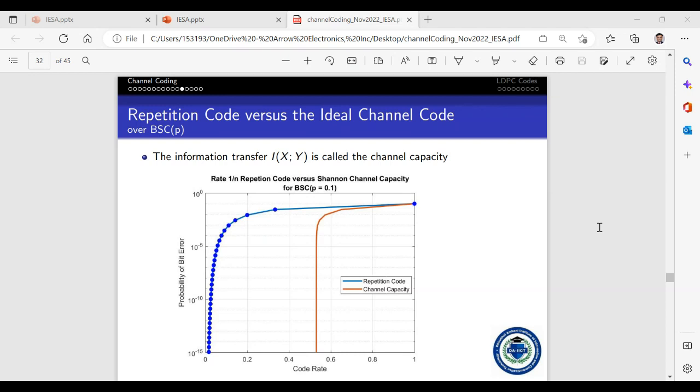If you have an equal number of zeros and ones, the majority voting decoder will get confused. But when you repeat each bit an odd number of times, it can never happen that the number of zeros and ones that the receiver gets are equal. So there is a slight performance benefit of repeating a bit an odd number of times. I hope that answers the question.